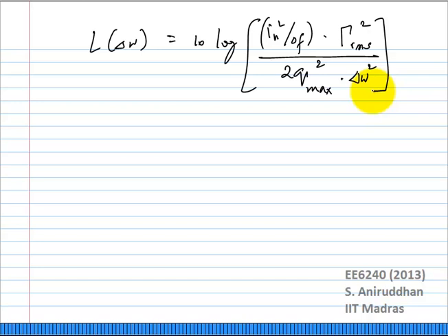If the oscillator output is cos omega t, the gamma is minus sin omega t. The RMS squared is half. You can go with this and figure out an expression and compare it to what you had earlier. But the basic idea is, this gives you a nice expression which takes into account folding due to time variance.